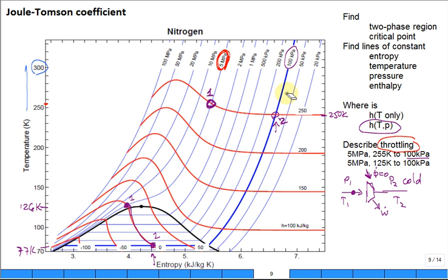It's isentropic. If it's isentropic, reversible, the best turbo expander you could design. Reversible, adiabatic, it's isentropic. What about that outlet temperature? Where's it going to be? Is there a big difference in the temperature now coming out versus the previous case? A huge difference, true? That's why they have turbo expanders in cryogenic refrigeration applications. You can see it right here.